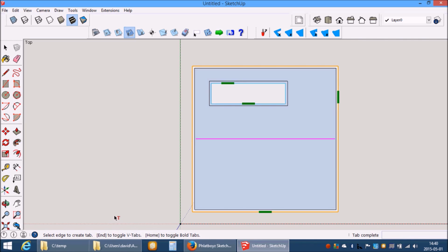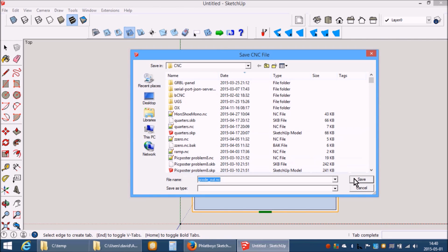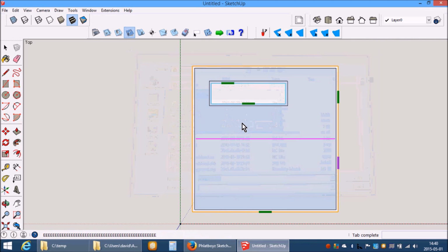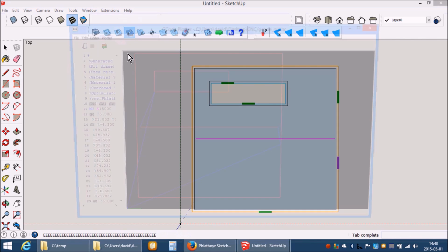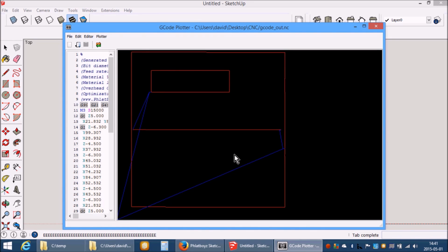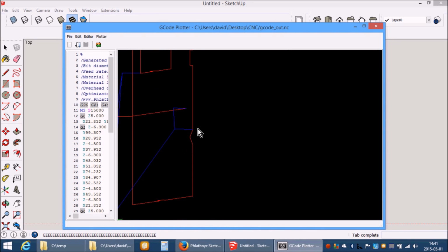The cursor displaying a T is normal tab. V is obviously a V-tab. We'll place a V-tab there. In the case of a V-tab, the edges of the tab will not be a sharp up and down movement, but instead will be in the shape of a V, as you can see here.